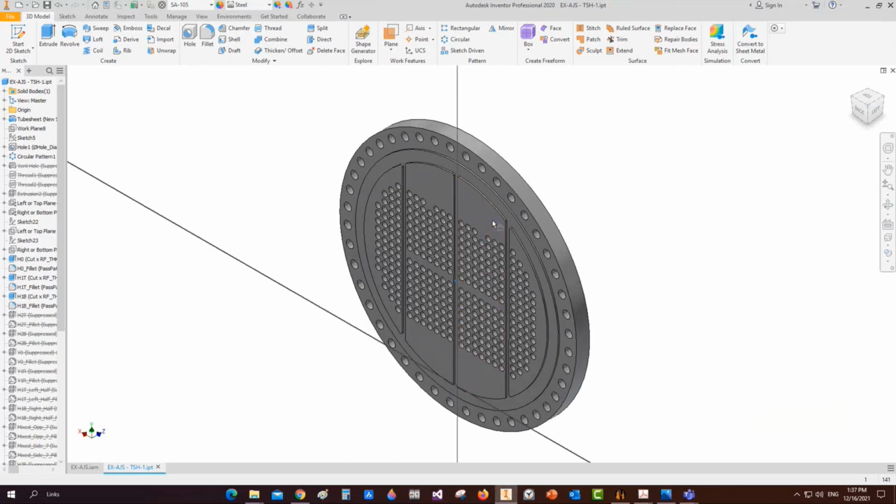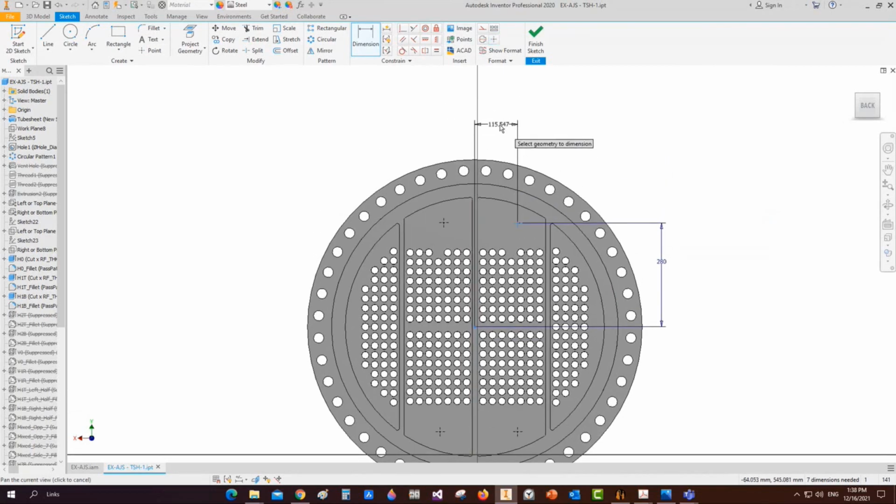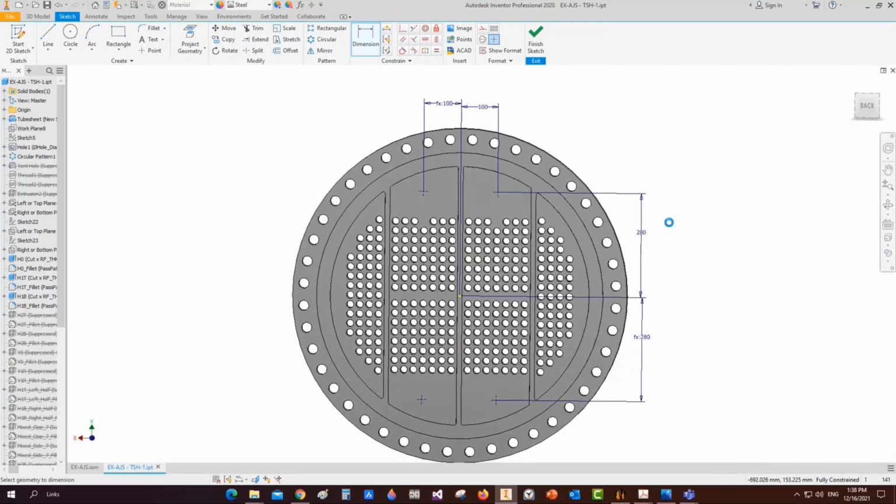If we select this surface, for example, you can add 4 points like this and define the location of each one. So let's make it this, for example, like that, and from the center line, and let's make the others. Okay, so let's define the offset from here. Looks like this. Now we have those 4 holes with the same dimensions.